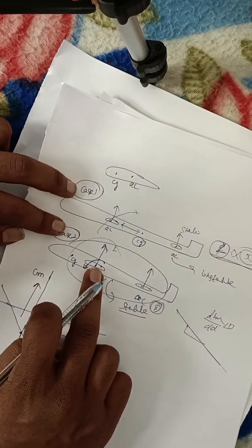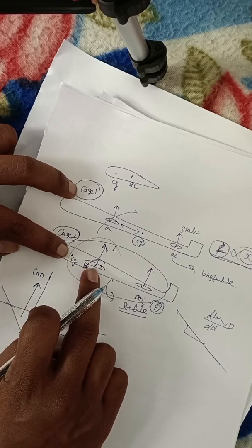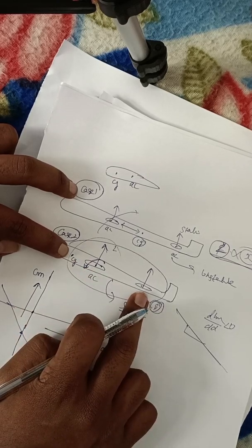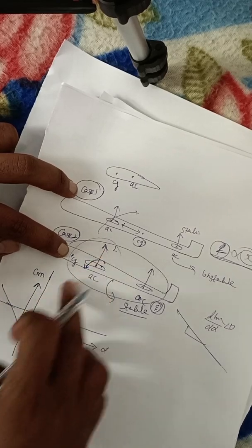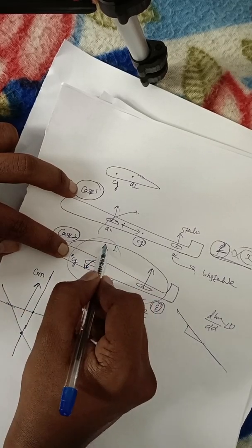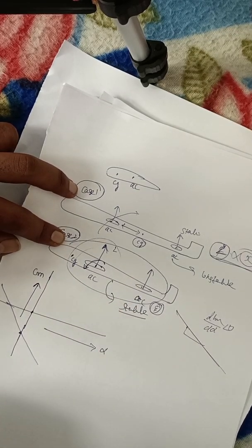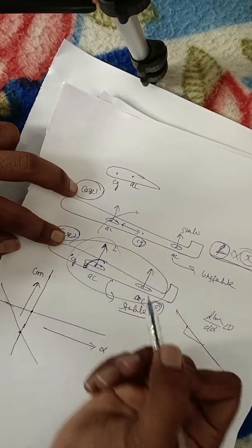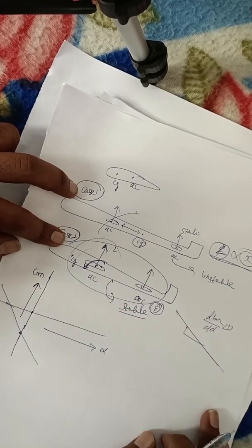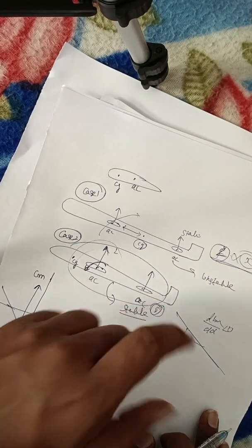Understand easily. When alpha is equal to 0, in this condition, if I place the CG point ahead of the wing aerodynamic center and tail aerodynamic center, this will create the negative moment. What is the moment at alpha equal to 0? Of course, if this is a cambered aerofoil, this will also generate some negative moment about the aerodynamic center, which is also nose down. It is very less.